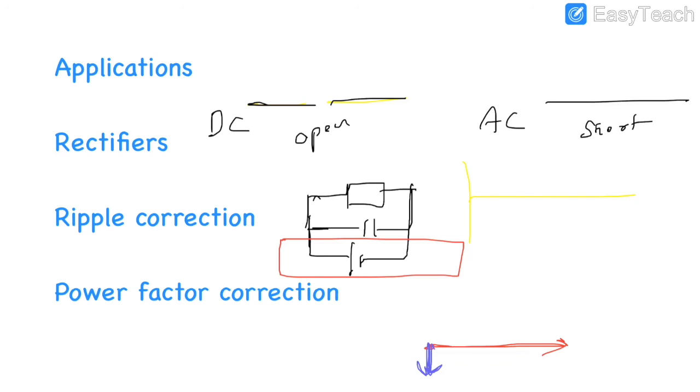That can be another video sometime. But ideally, you want these to be parallel. If you have a resistor, they're pretty much in parallel, so your voltage and current phasors are going to be pretty much in sync. All right. So when you have a lagging power factor like this, by adding a bunch of capacitors to your circuit, you can try to minimize this and get the current phasor in line with the voltage phasor. So that is another application of capacitors. Without ado, let's go ahead and get to solving some problems. All right.